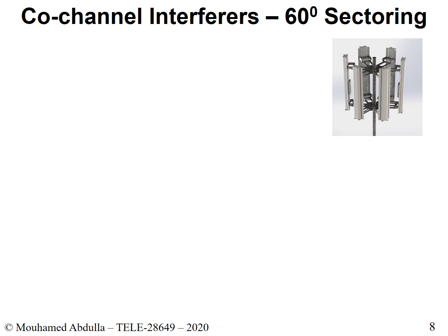So this, again, you'll see it everywhere around cities. Major cities, you'll have this kind of setup, especially in dense regions. So if we draw the cells that we had before, but now instead of keeping it as one cell or splitting it into 3, we split it into 6, and we give them names. We call them A1, A2, A3, A4, A5, and A6, and we look at its coverage region. For instance, if we look at the antenna for A1, it would only have this coverage area, and in this coverage area, it will only see 1 interferer.